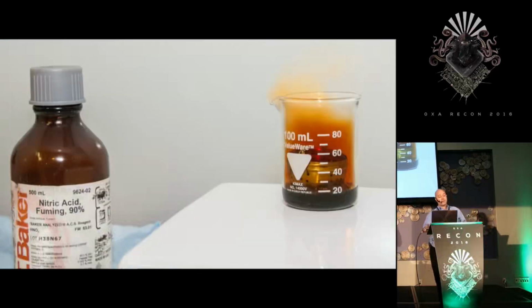To look at the chip under the microscope, I have to decapsulate it, so I use fuming nitric acid for this. The chip is immersed in heated red fuming nitric acid. This reacts with the plastic packaging and removes it. The chip is then rinsed in acetone and cleaned with isopropyl alcohol in an ultrasonic bath, and then you have a nice, clean, bare die.